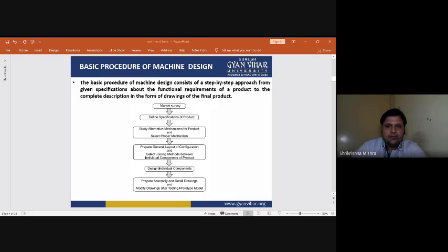Number one, a mechanism involving the crank and connecting rod, converting the rotary motion of the electric motor into the reciprocating motion of the punch. Number two, a mechanism involving nut and screw, which is a simple and cheap configuration but having poor efficiency. Number three, a mechanism consisting of a hydraulic cylinder, piston, and valves, which is a costly configuration but highly efficient. The alternative mechanisms are compared with each other and also with the mechanism of the products that are available in the market.